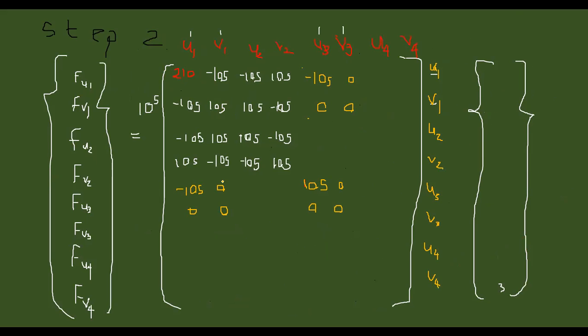For example, you can even draw that matrix like this, right? Divide it into 4. This is from u1 v1, u4 v4. This is the part which is to be added, u1 v1, and these rows are u1 v1. So these 4 elements will be added to these 4 elements, because it is also u1 v1, u1 v1.